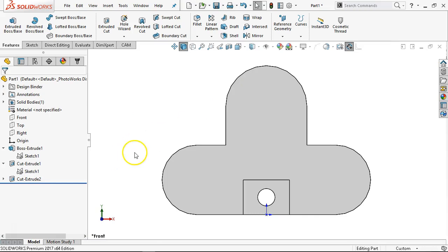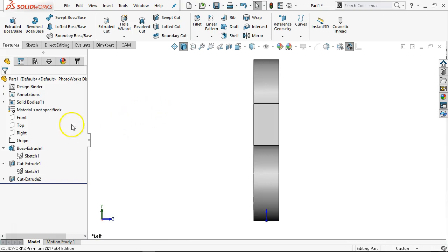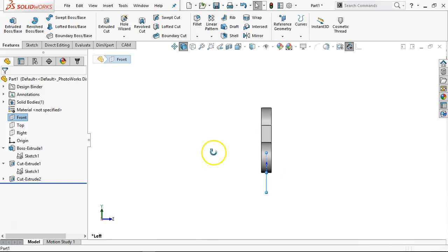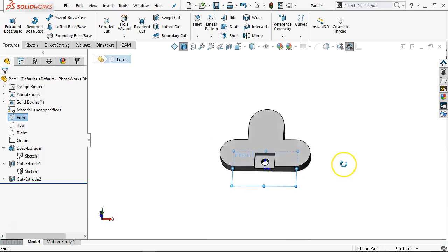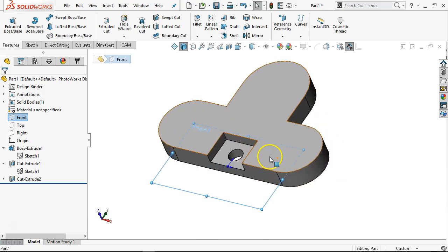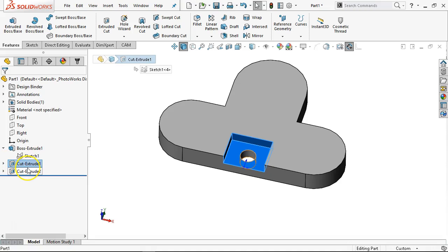All right, so the test then is when I want to make changes. There we go, 3. And we go find the front plane because we set it at the mid plane. The 1 inch is split ½ inch forward, ½ inch back of the plane that we were sketching on. And then I use that a little bit to the advantage. I don't know that it is really that big of a deal. Sharing the sketch is probably a little bit easier, but there are going to be times where you would want to convert the entities that you've already generated.